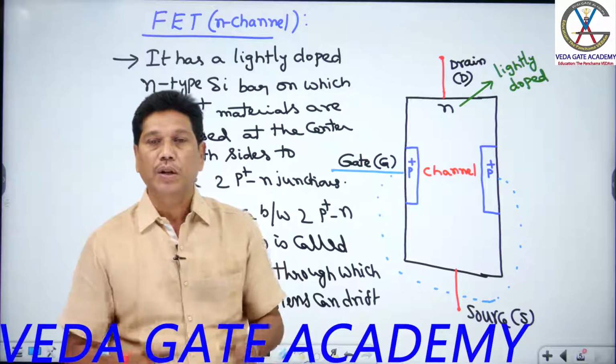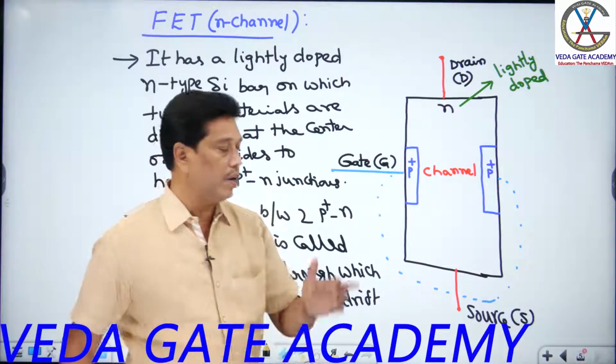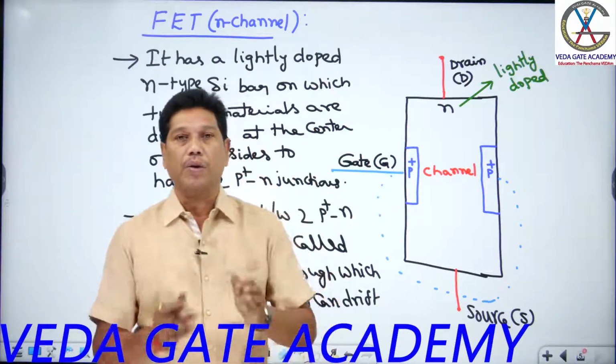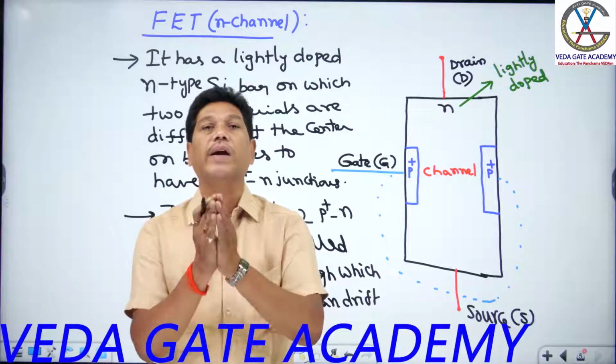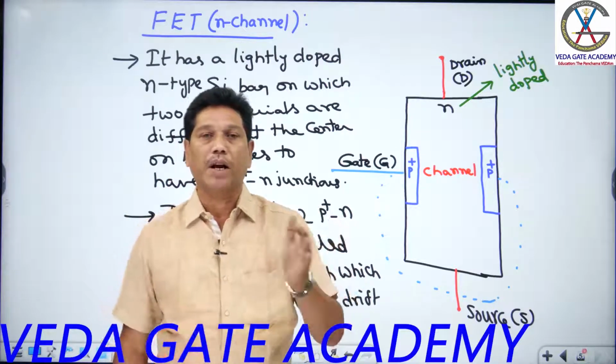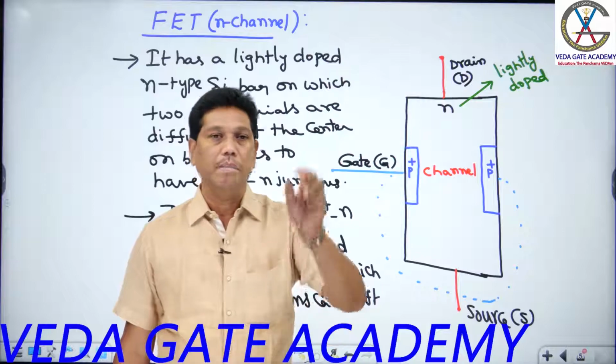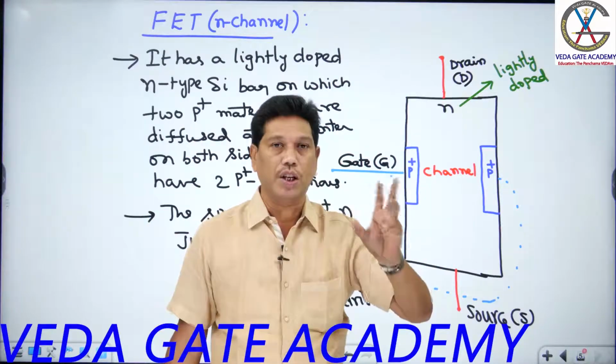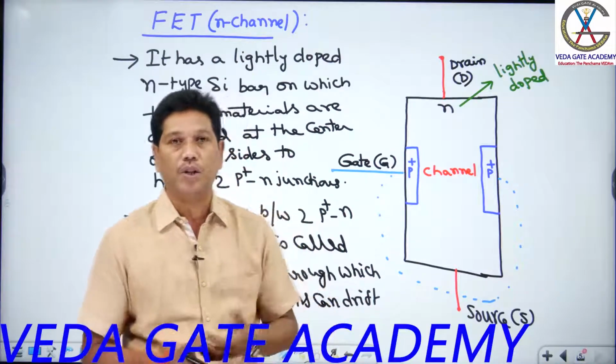Understood my option? So in FET as well as MOSFET, there is one flexibility. Source and drain are interchangeable, but you don't say emitter and collector are interchangeable. So in BJT, emitter and collector are not interchangeable, students, but in FET as well as MOSFET, source and drain are interchangeable. You understand what the meaning of interchangeable, students?